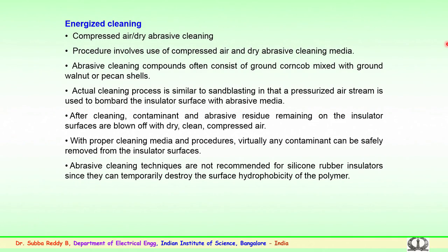So, that was about the de-energized condition. Now, we discuss the energized cleaning, that is, during the power supply which is on. Where hotline tools or hotline maintenance are being employed for the cleaning of insulators. Here again, compressed air and dry abrasive cleaning is normally used. This procedure involves the use of compressed air and dry abrasive cleaning media.